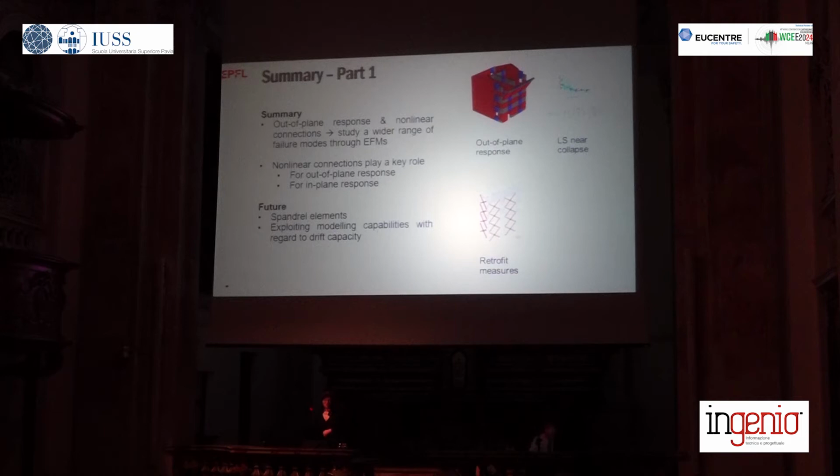So in the future we really want to invest more in the spandrel element modeling and also exploit some of the modeling capabilities that we haven't really used yet, that Francesco has coded into that macro element, and this is in particular with regard to the drift capacities, making the drift capacities a function of the axial load ratio, the shear span ratio and so on. So this is for the future to come.